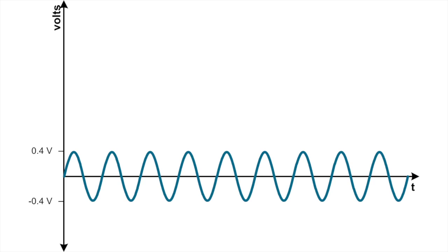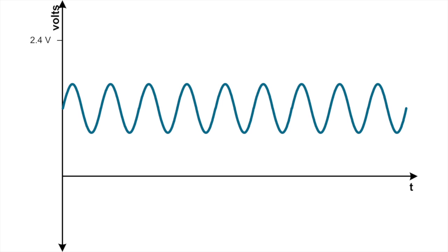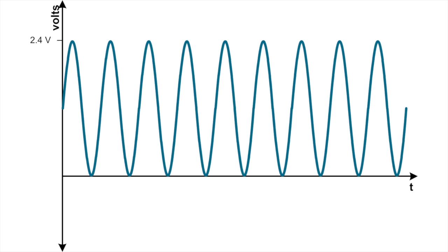And the headphone jack itself will create a signal that is fairly small amplitude and centered around ground. Our ADC on the MCU only sees things between ground and the voltage reference, which is about 2.4 volts. So we're going to need to apply first some DC offset. And then we're also going to do a little amplification so that we can see the waveform easily on our tiny little LCD screen. Oh look, it's so cute!